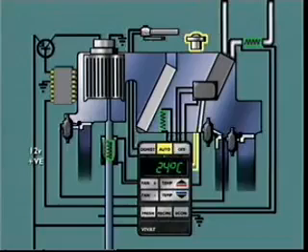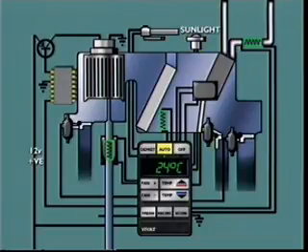The sun load or solar sensor is located on the dash panel, where it is exposed to light entering through the windscreen of the vehicle. This sensor is a photodiode. It becomes more conductive as the light intensity increases. When connected to the electronic control unit, a change in light intensity is registered as a change in voltage.